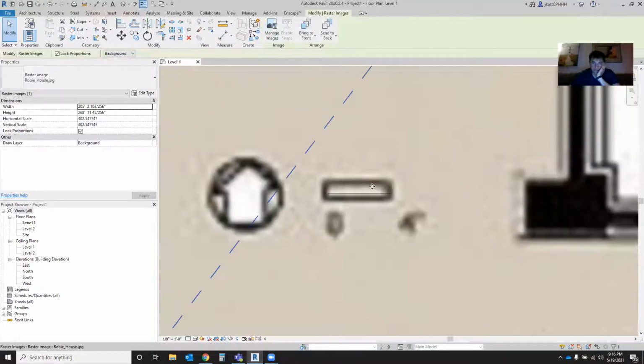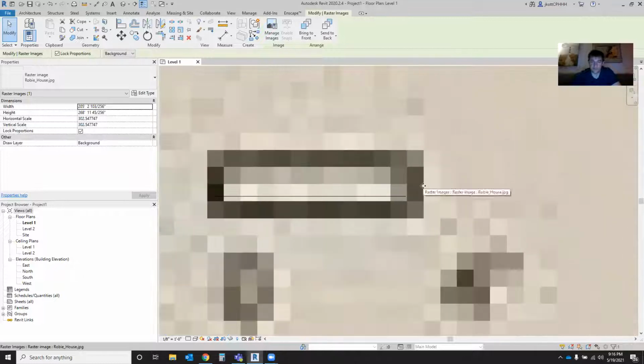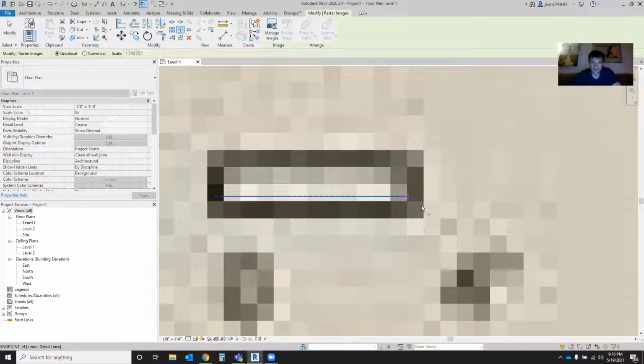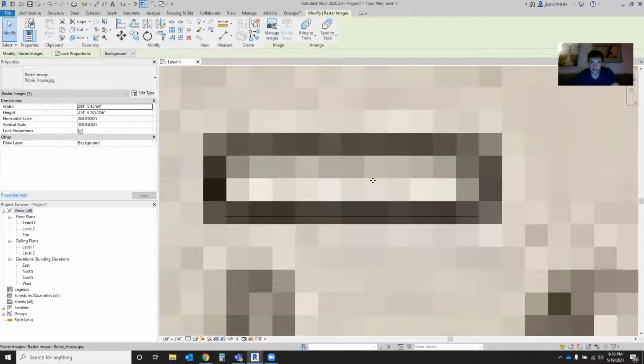We can scale it that way. That's convenient. So you just click scale right here, and then you can click on the photo and scale to a certain point. So that's much better. In fact, let's even scale it down a little bit more. We go from here to about here. Okay, so this is close enough, and we can adjust this later as we work.